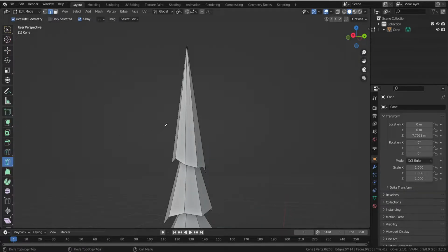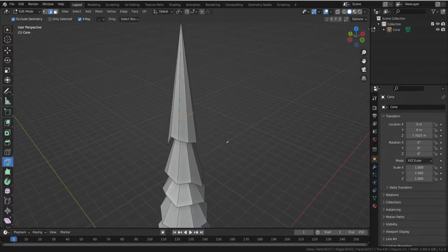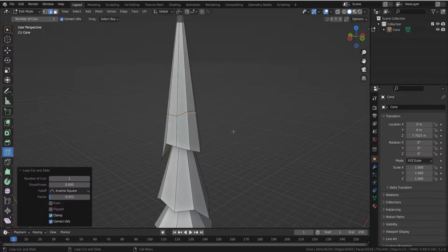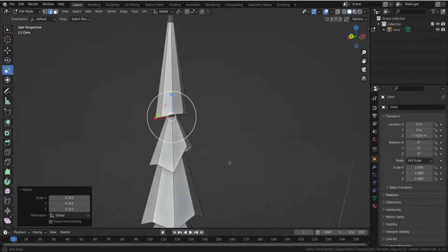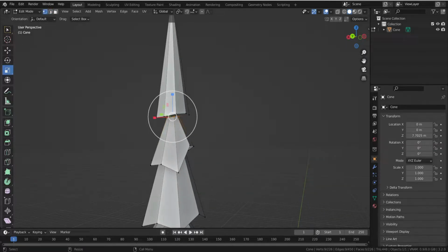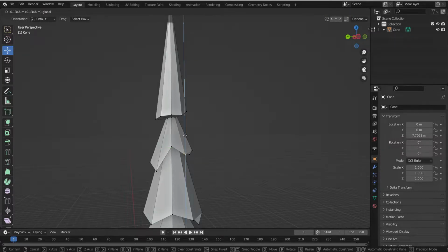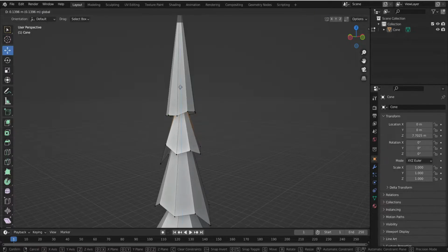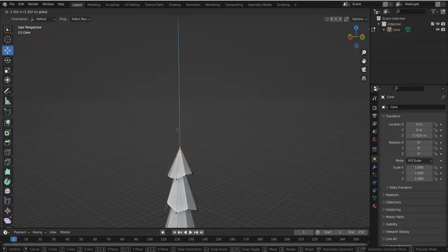In the meantime, what we're gonna do is make a couple of more knife cuts right here, so that we can break it up into much easier segments. Okay, now we're gonna select the top bit. Okay, so if your knife cut has problems, you can simply select those points using the vertices and fix them. Okay, select the top bit and reduce its height.